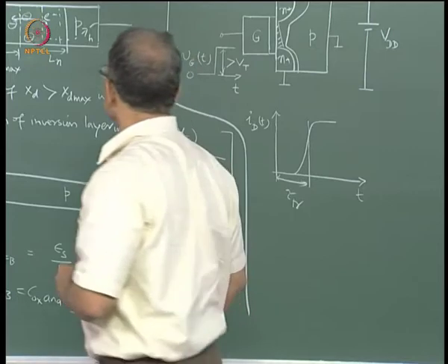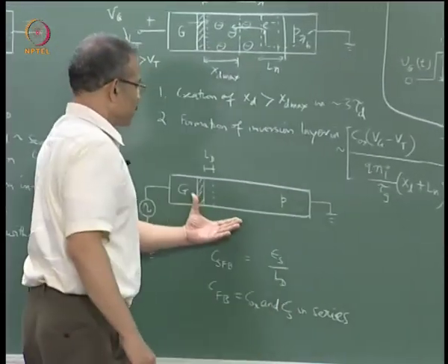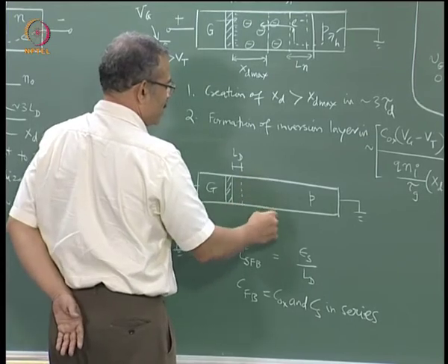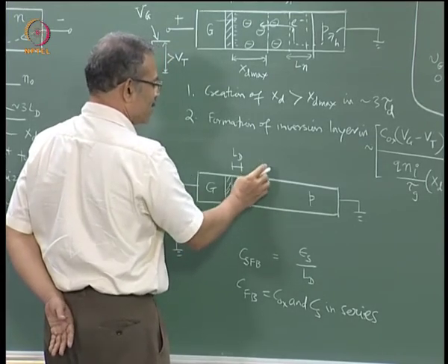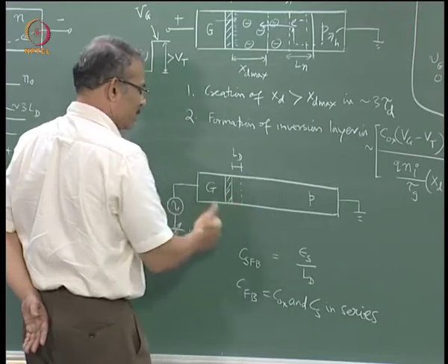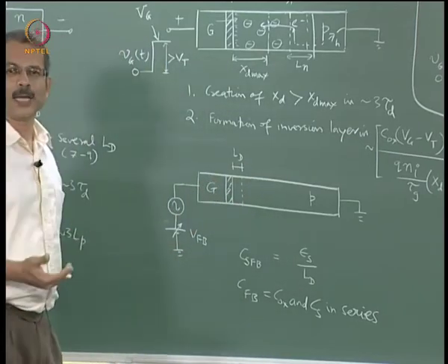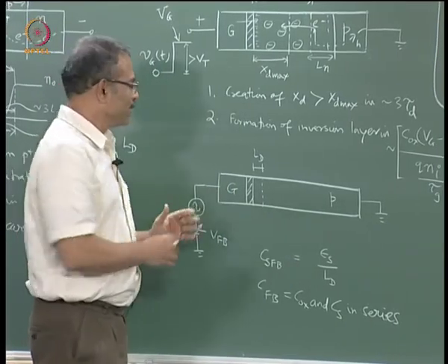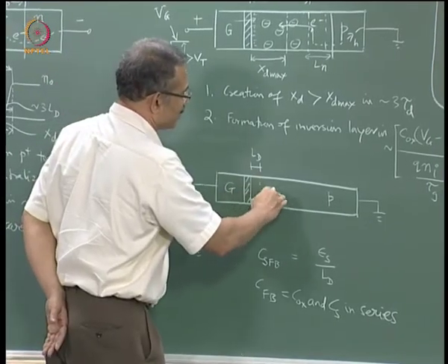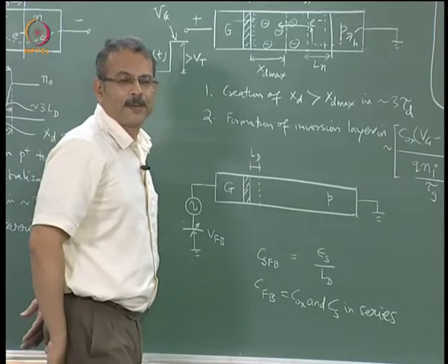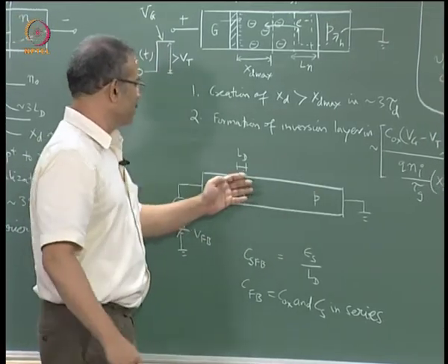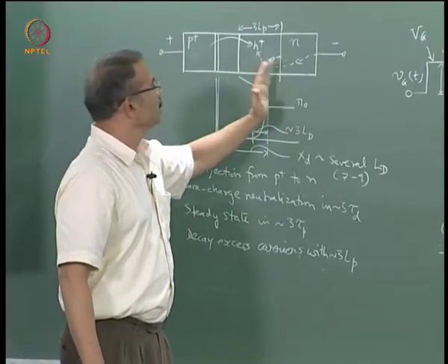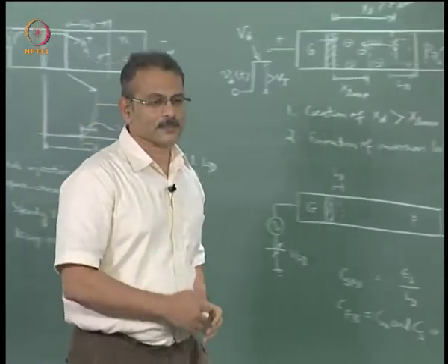So for example if you take this MOS capacitor, as you change this voltage your depletion region changes, and that is how you can find out what is the doping at the edge of the depletion region. There is a formula, you must have studied this formula in the first level course. Now we are talking about that CV measurement to measure the doping profile. So what is the doping variation in the X region in this bulk, or for example if you take the p-n junction, what is the doping in the lightly doped region, what is the profile here.